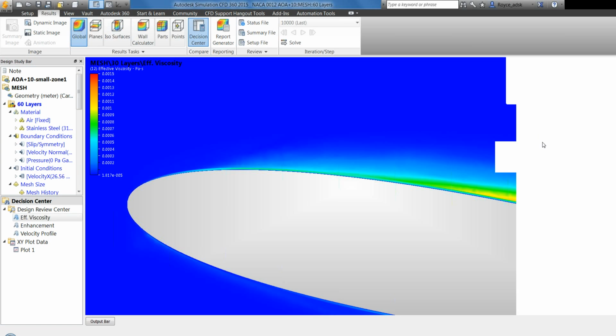Okay, so that's probably what I would do, but I would still probably leverage about 5 to 10 layers of mesh enhancement when it comes to SST, k-omega. If your heat exchanger is actually all gas-based of some sort, then you can just go back and use k-epsilon with probably 3 to 5 layers of mesh enhancement and do pretty good at that point.